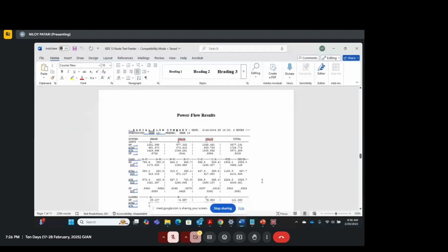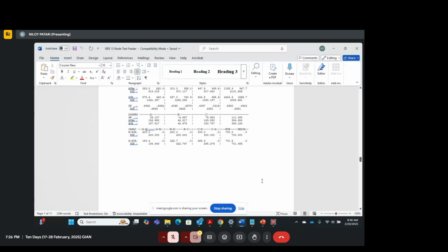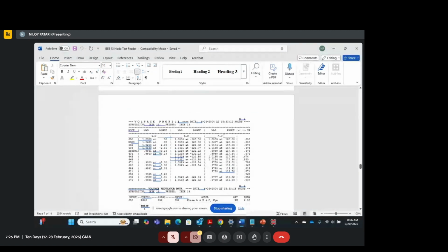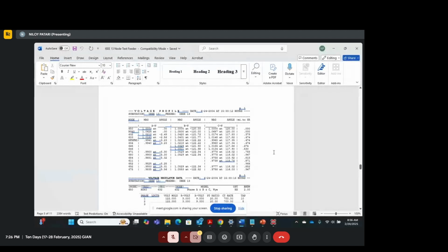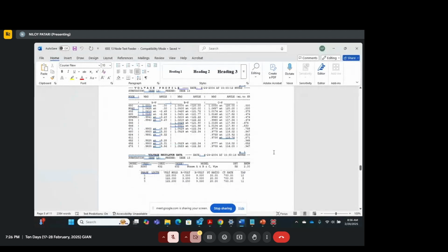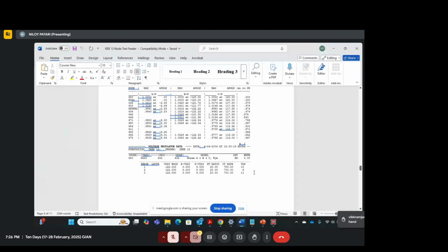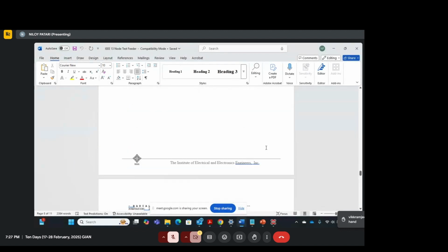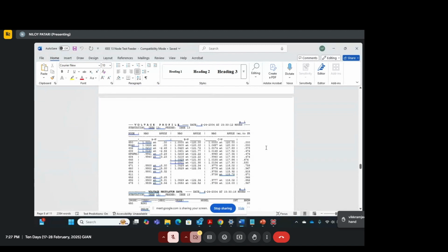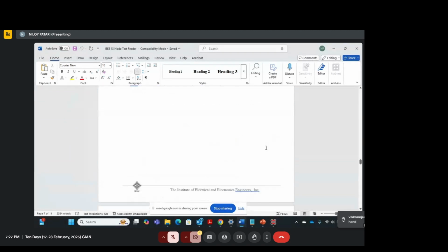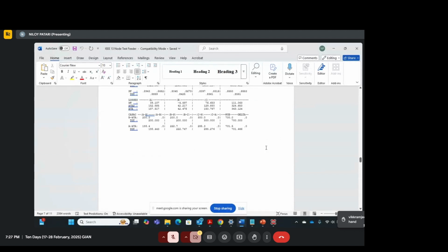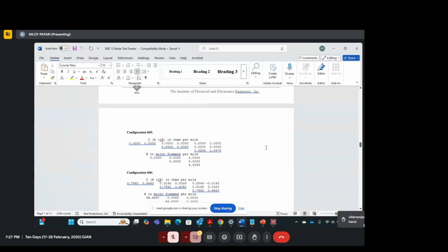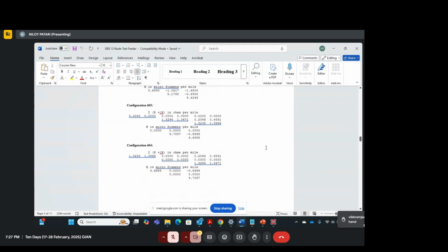There is some bug or something you're doing wrong. So these power flow results will show you the voltage profile, right? It shows you how the voltages look, what the voltage regulator data is, and at the end of the day, how the taps look for each of the voltage regulators. The reason for showing all this, the docx document, is that whatever is written in this document, you have to exactly copy that in OpenDSS, right?